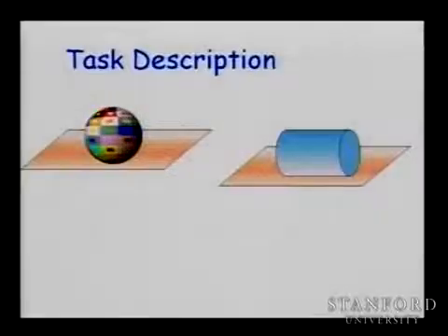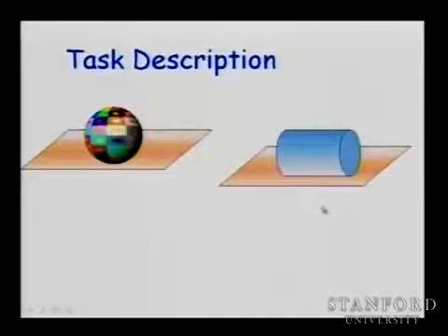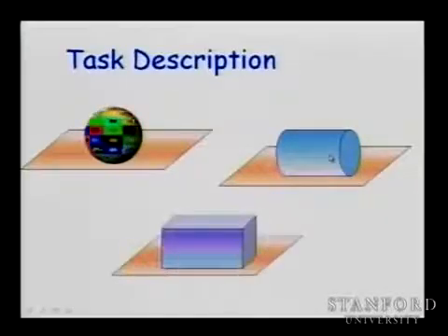2? 5. You lost, yes, 2 in position, and then you still do rotations. You still have those rotations. So you lost 1 degree of freedom by this contact constraint. How many degrees of freedom do we lose here? More than 1? 2. We lost the z-axis, and we lost the rotation about the y-axis, this axis. You cannot rotate about this axis. Okay, how many did we lose here?